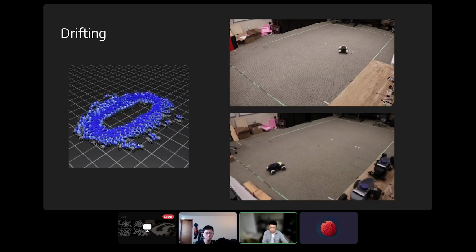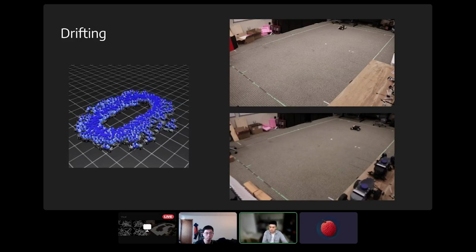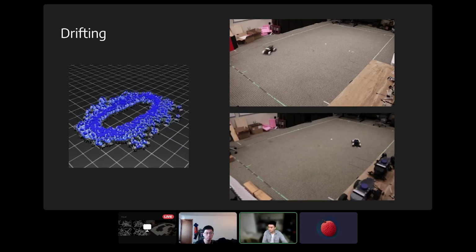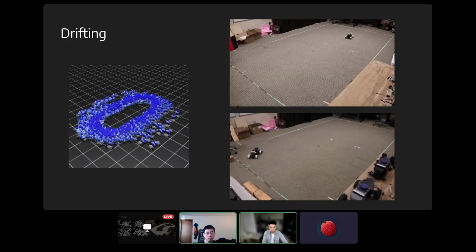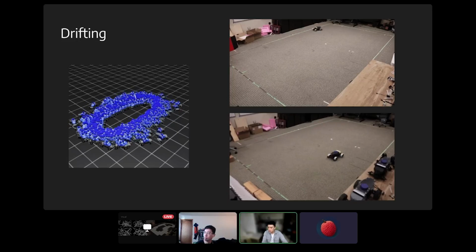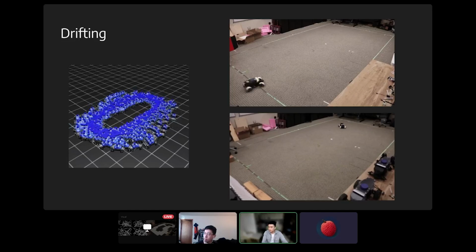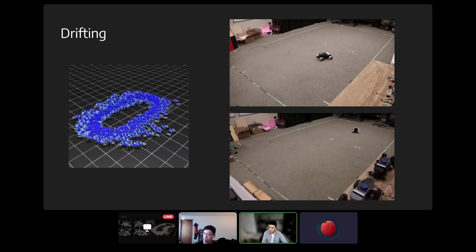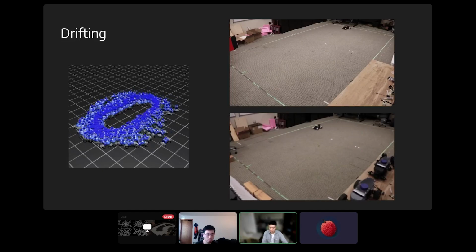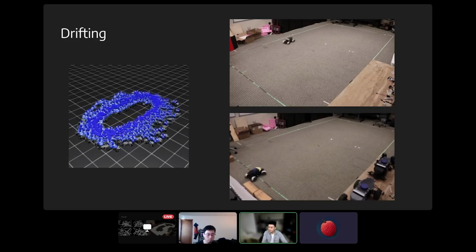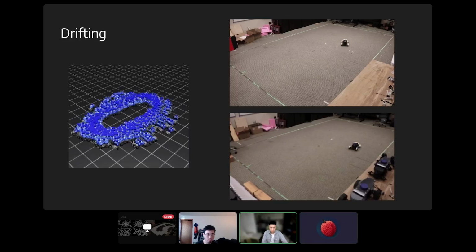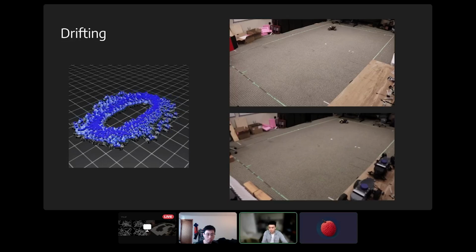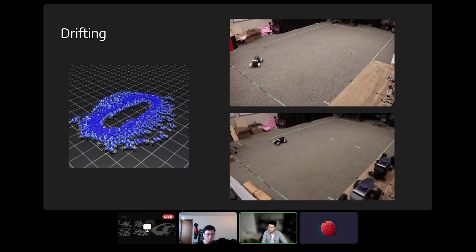It's getting the steering linkages correct, it's getting the suspension correct, it's getting the friction correct, and then in simulation, it's finding the correct rewards. You can even push the robot randomly in simulation, which makes the simulation quite adversarial to the robot. I think it's a product of all of these things.